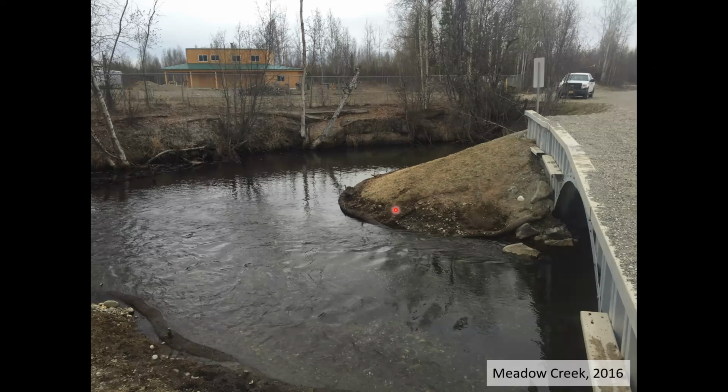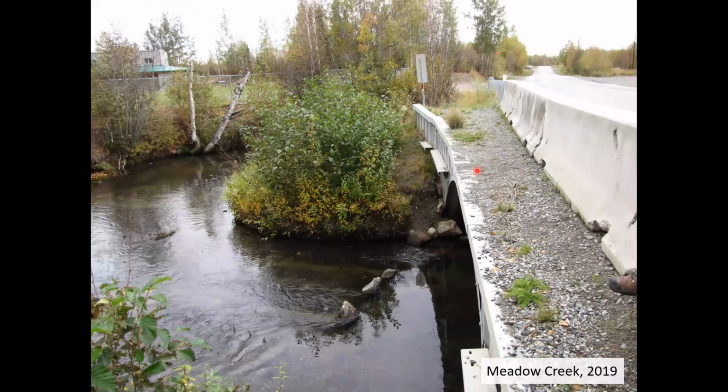So in this case, it was a workshop. We did a coir log around it, 1 brush layer, potted alders, and then a special type of hydroseed was used. So this is what it looks like in 2019. And this is, again, one of the sites that people do come down, walk and fish, especially local kids. So keep that in mind as you're working on these projects, especially if you can prevent people from walking on them, especially the first couple of years. That's really great. Understanding, though, that lots of times at these fish passages, you can't always stop the public from walking on them.